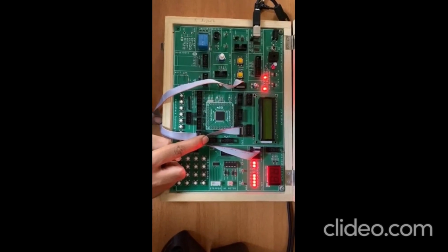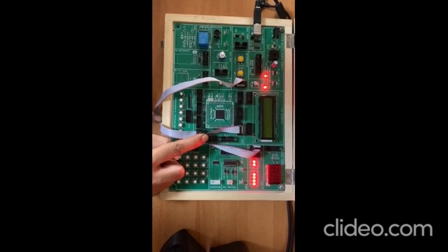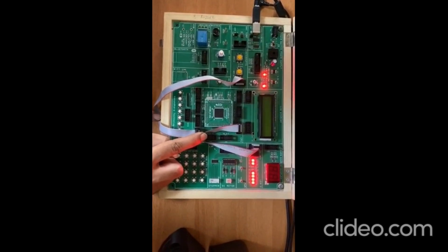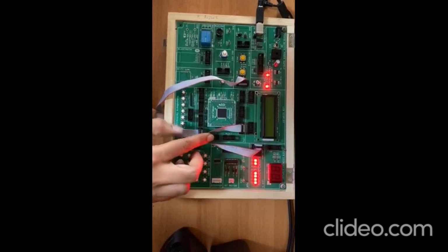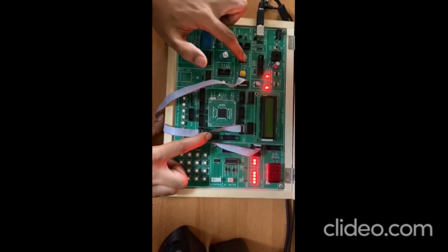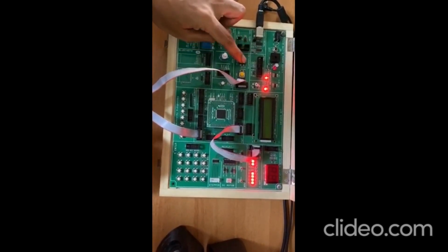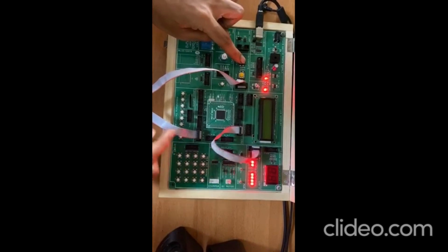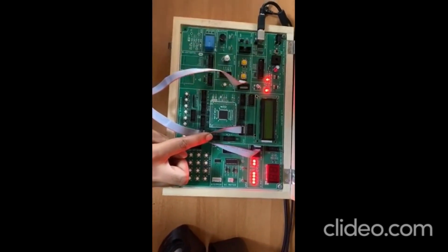After dumping the program onto the kit, make the connections using flat cable with J26 connected to J13 and J17 connected to J1, which is connected to the LEDs over here. So you have two external interrupts, interrupt 0 and interrupt 1. So you can control the LEDs using the interrupts. If you press external interrupt 0, you can see the toggling of one of the LEDs, and if you press external interrupt 1, you can see the toggling of another LED.